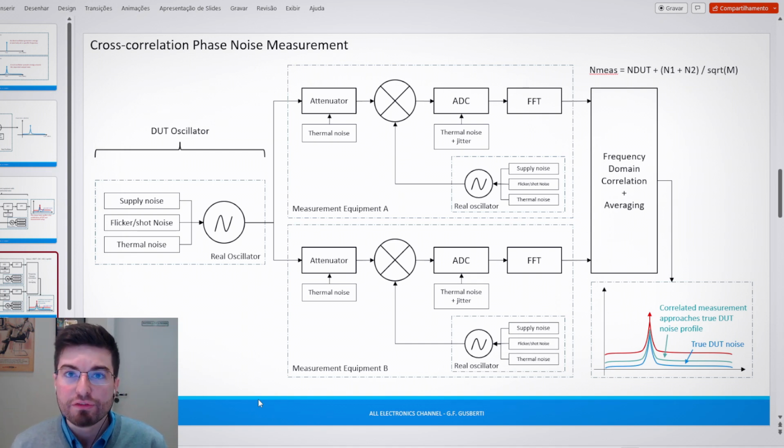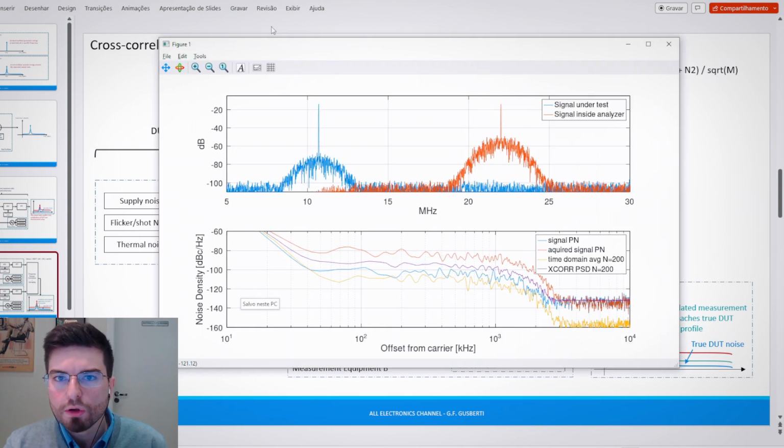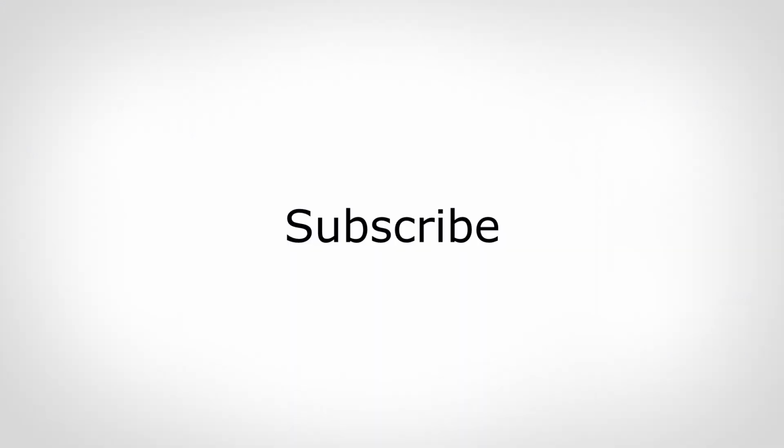I'm Gregory, and in this video you're going to understand how phase noise measurement works using the cross-correlation method, allowing the measurement of phase noises lower than the analyzer phase noise. Very interesting. I also wrote an Octave simulation that virtualizes the measurement using the cross-correlation, simulating an analyzer measuring an oscillator, and we are going to study the differences and the improvements in phase noise measurement using the cross-correlation method. Take your coffee and come with me.